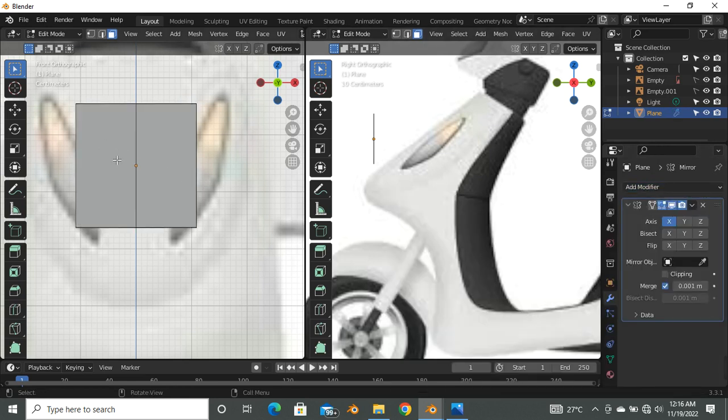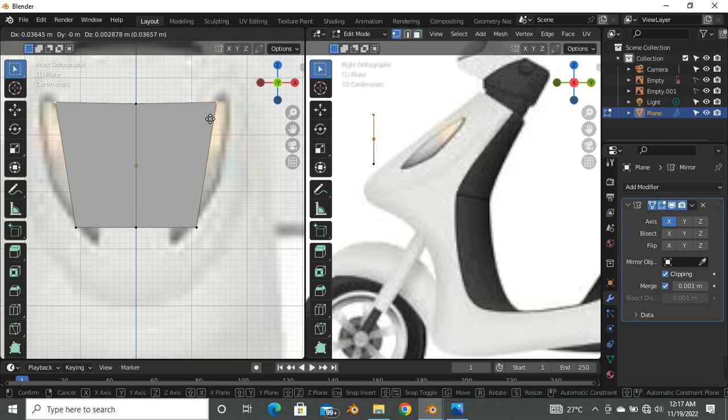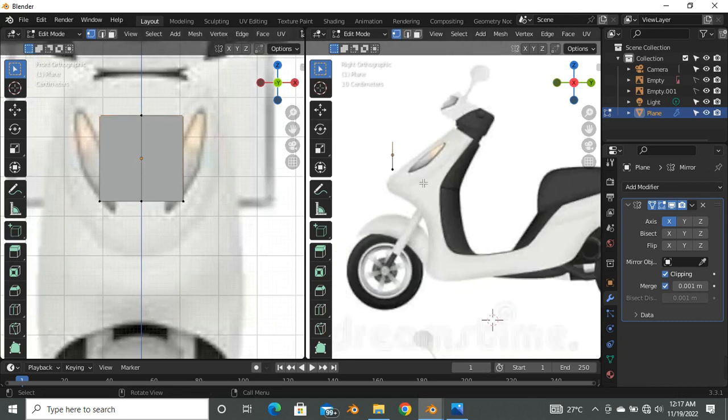So now I have a mirrored plane here, and I'm going to enable clipping also, and go to clipping and caging. And if I say 1 on my keyboard for vertex selection and say G to grab, you can see that whatever thing I do on this side affects this other place. So now it's very simple.